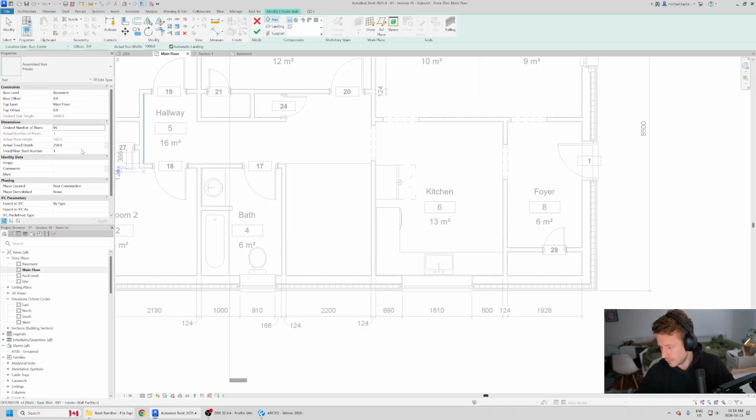But just give me one second here. 200, 255, something like this. So typically what I do is, if you want to be crystal clear about what the OBC says, make sure you check your codes, your local codes, wherever you are. If you're using an NBC, if you're using an OBC, I'm going to real quick look up OBC Part 9 stairs, stair riser, and let's do it. So between 125 millimeters and 200. So that's a pretty steep stair, if I'm being honest. So 200 millimeters high. It's pretty high.